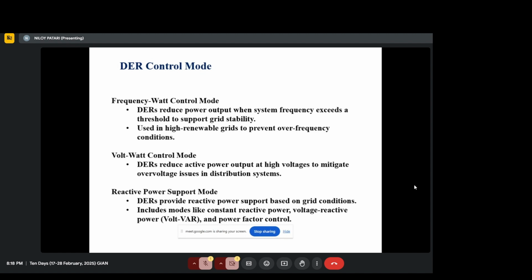Why is that? Because this kind of disturbance can be taken care of from the power system side, by the inertia of the system, which is saved in the rotational energy of synchronous generators, right? So these disturbances won't matter much because the inertia of the system is huge. Now, if the inertia of the system is not huge, or if you are not able to control power flow depending on frequency, then you have problems, right? So this is what dynamics really mean.